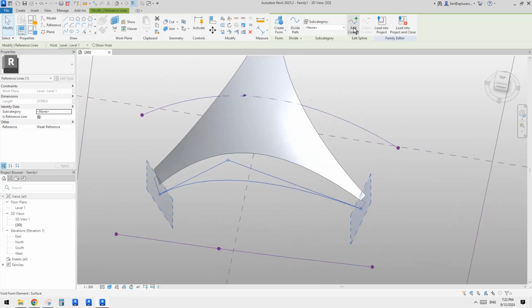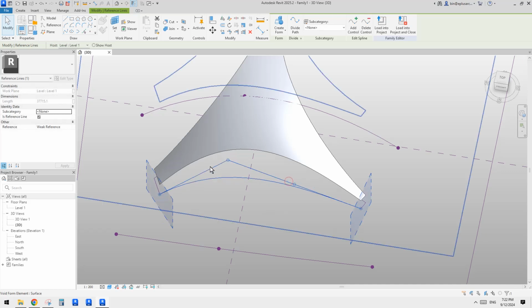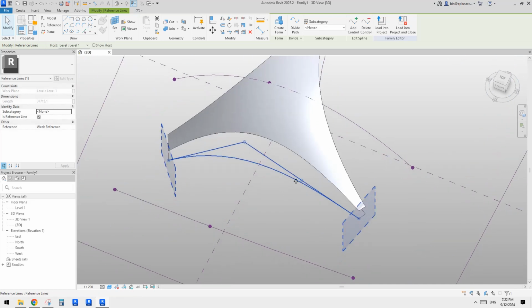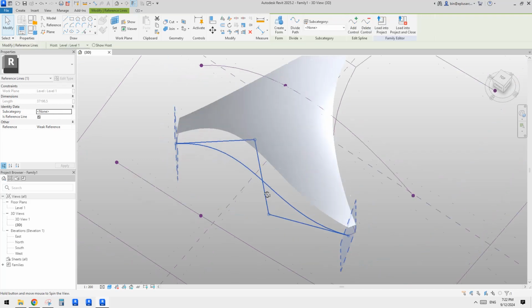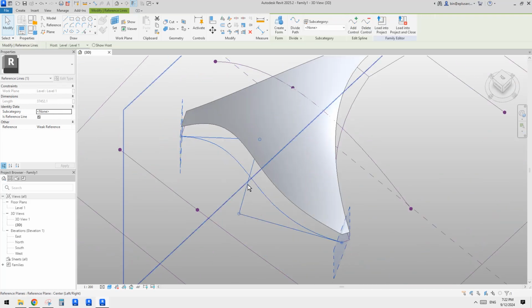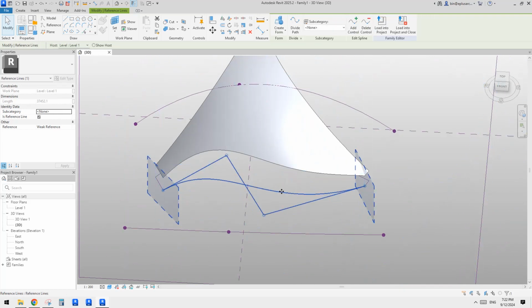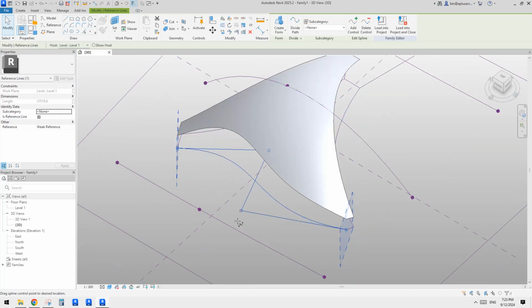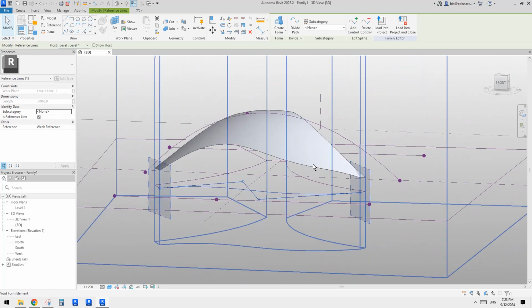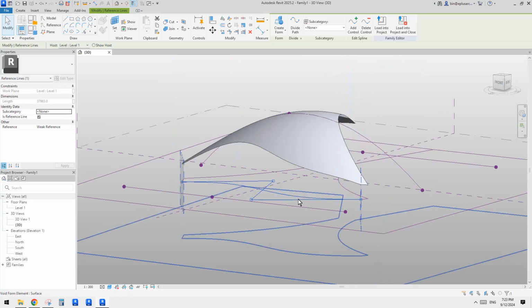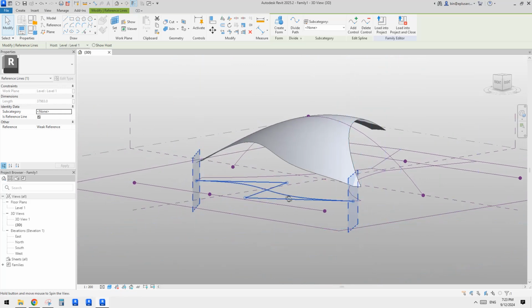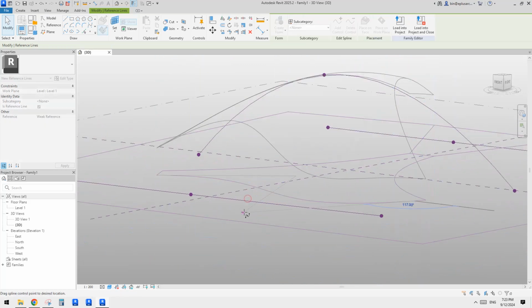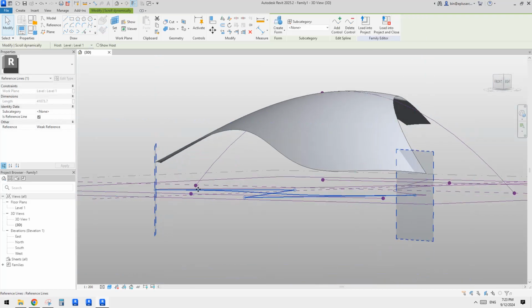And then you can also add control points, because this is a spline. It's slightly different to the spline through points. For spline through points, you need to place a point, you draw face onto the line and make it driving. But for spline, the difference between spline and spline through points is that if it's a spline, it can only be two-dimensional.